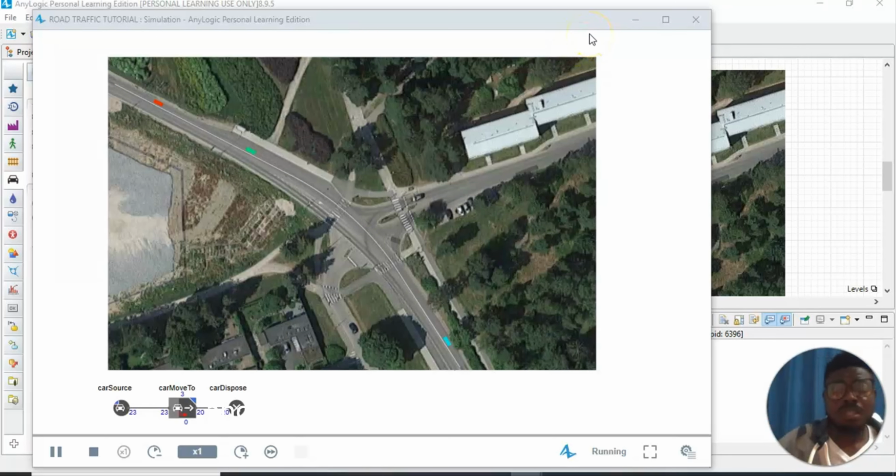And after doing that, we reduce the opacity level by making the road a little bit semi-transparent. After that, we change the properties of the road. After changing the properties, we can increase the width of the road. Instead of having it as 25 centimeters, we increased it to 35 centimeters.